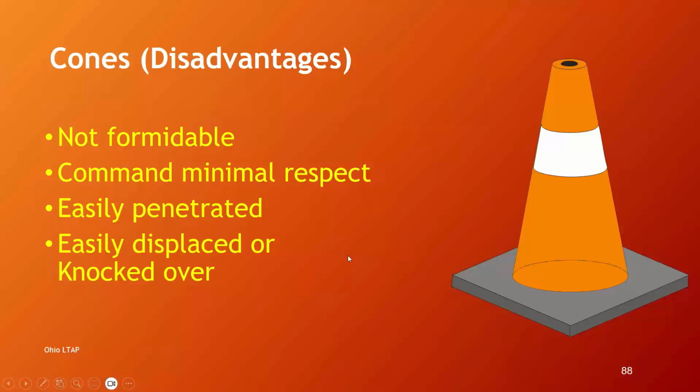It's nice if you have that grass lawn area between the sidewalk and curb and gutter, but if you're working in a downtown area of a city, sometimes you have to remove parking and put your signs there. And an easy trick to placing signs is to hang them on an orange drum. That's what we did when I was at the city.